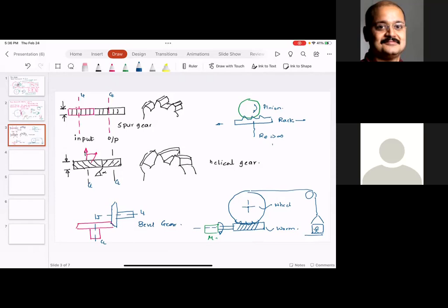That timing chain is continuously submerged in an oil bath, and that extends the life of the timing chain. Because of that, the timing chain is cooled, cleaned, the coefficient of friction is reduced, and that allows timing chains to go up to 100, 150, 200,000 miles without any problem.